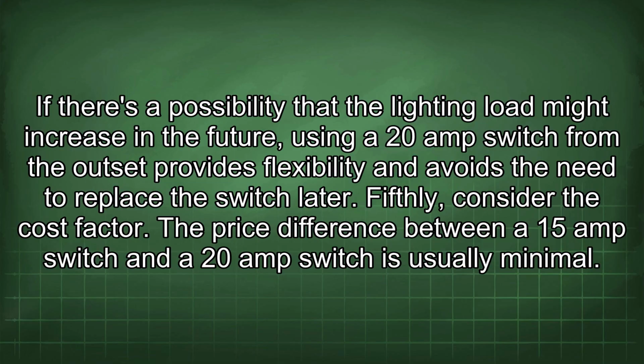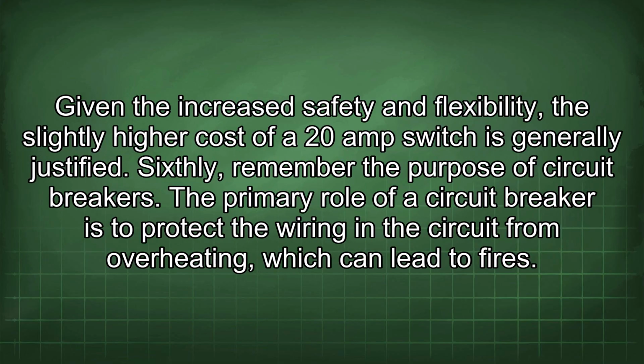Fifthly, consider the cost factor. The price difference between a 15 amp switch and a 20 amp switch is usually minimal. Given the increased safety and flexibility, the slightly higher cost of a 20 amp switch is generally justified.